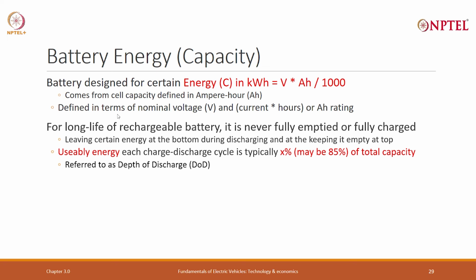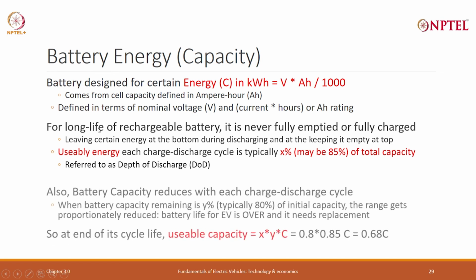For long life of a rechargeable battery, it is never fully emptied or fully charged. I mentioned that to you. Leaving a certain amount of energy at the top, basically you never fully charge. Leaving certain energy at the bottom, you never fully discharge, and that is called depth of discharge. Usable energy is therefore a certain percentage of total energy, typically 85% of total capacity, referred to as depth of discharge. This is important. We will repeat all these things as we go on.